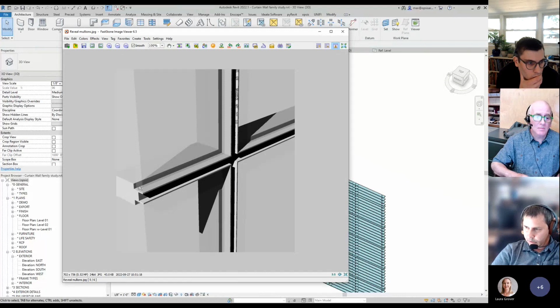But if you've ever tried to do this in a project, you know that this joint connection wouldn't really work this way, because you'd have either a horizontal or a vertical break in that. So really to get this to work, you'd want to build in that mullion within the panel family itself so that they start to join in this way once you join all the panels together.